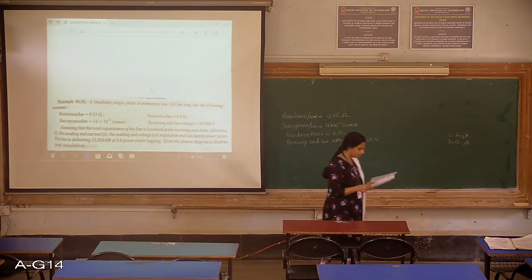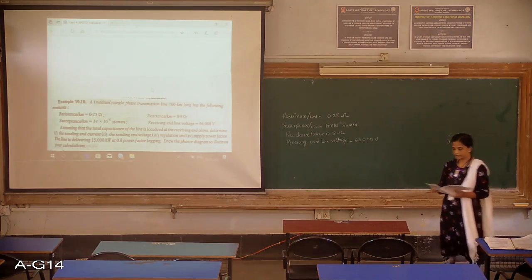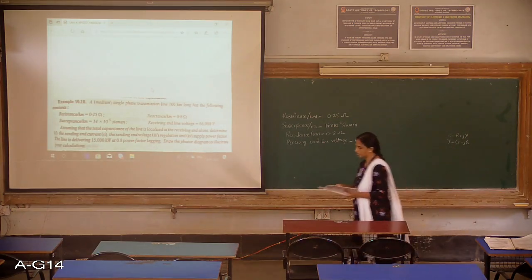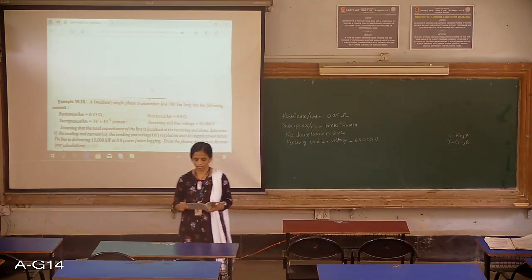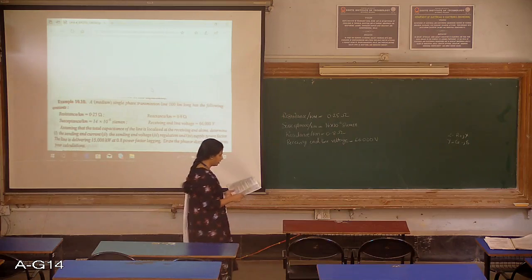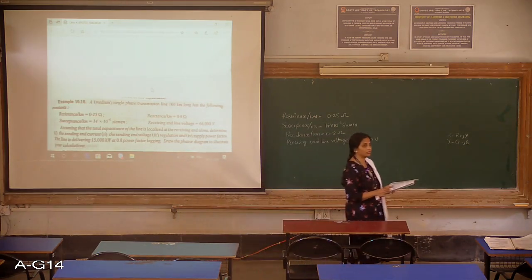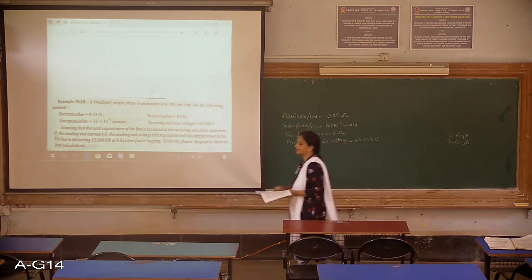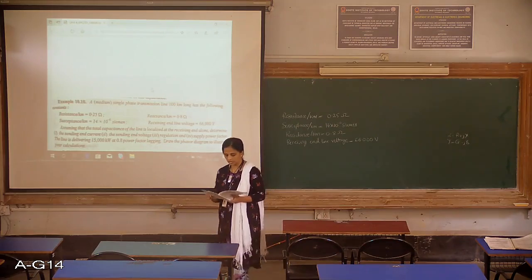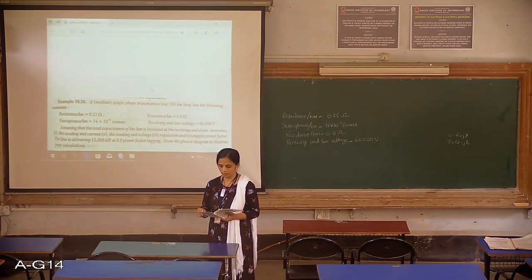Determine, first, the sending end current. Second, the sending end voltage. Third, regulation. And fourth, the supply power factor, that is, the angle phi s they want to know, so indirectly cos phi s. The line is delivering 15,000 kilowatts at 0.8 power factor lag.